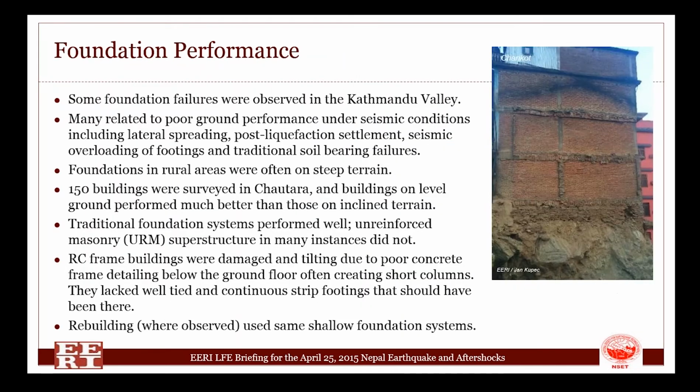Looking at foundation performance itself, some foundation failures were observed in the Kathmandu Valley. They generally related to poor ground performance under seismic conditions, such as lateral spreading and liquefaction-induced weakening of the soils that caused traditional soil-bearing capacity failures.